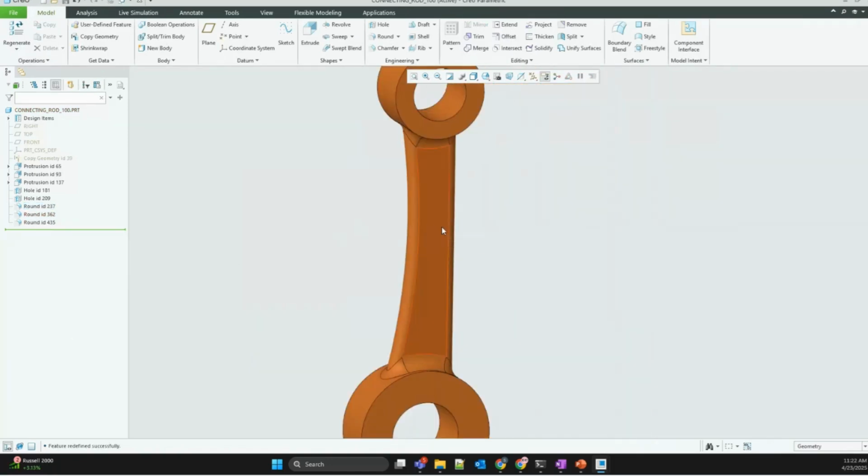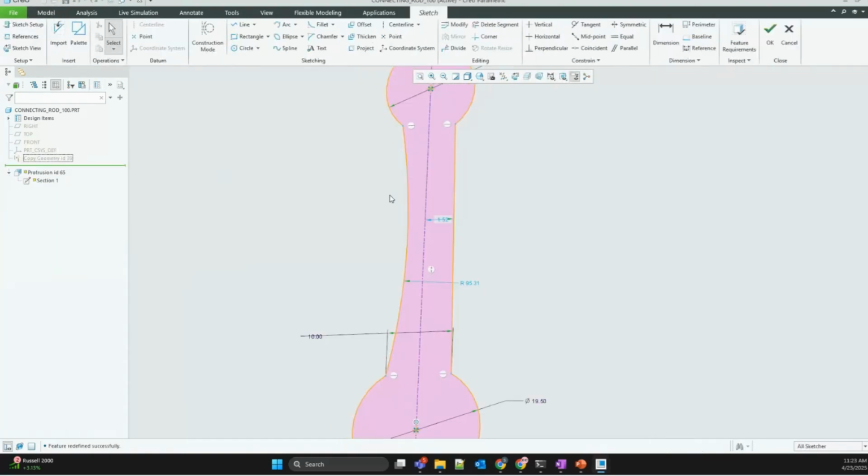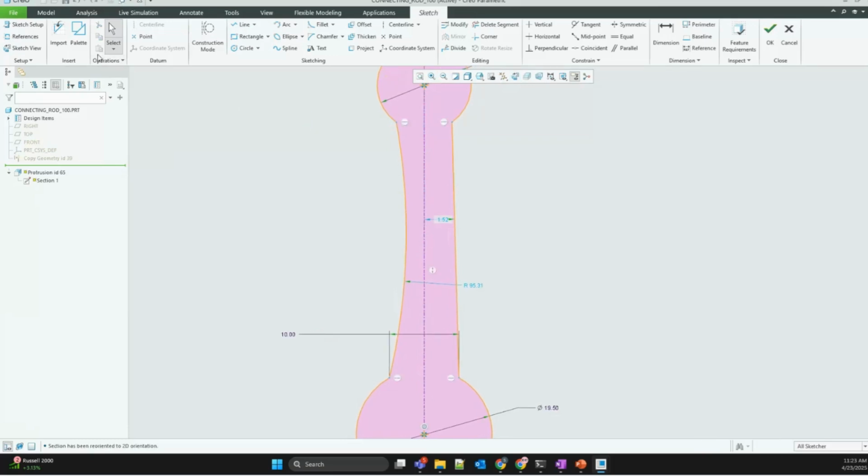So that's one way to create that change, but the proper way to do it with the replace functionality is what I'll show next. I'll go back into the sketch and I'll do the replace on this side as well. Now, before I delete this, I will not delete it. I'll have Creo do that for me automatically. But to do that, I will first go ahead and sketch arc. So I have the new arc, have the existing line.